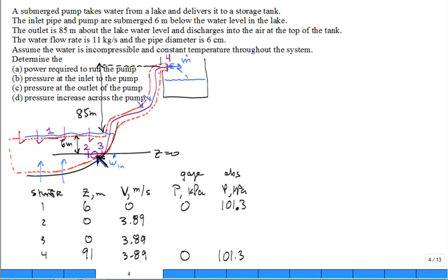Do this. Introduce a new control volume. What control volume would be helpful? Maybe I'll sketch it in color green. Come along here where it has the same boundary along 1, but then come down and cut right there at 2. And so the only two places there's water flow into that green control volume is at 1 and out at 2. And now we'll do conservation of energy balance for that control volume, where there's only 1 and 2 on the inlet, right?